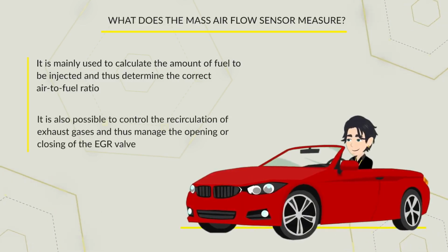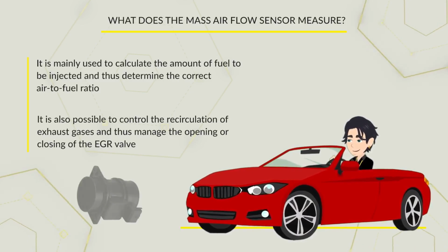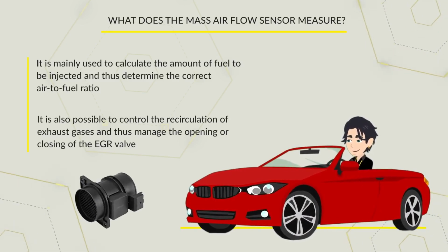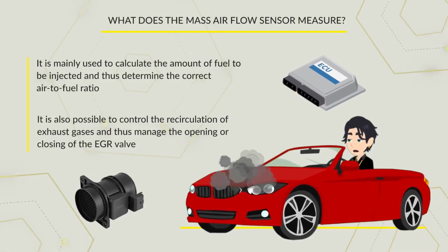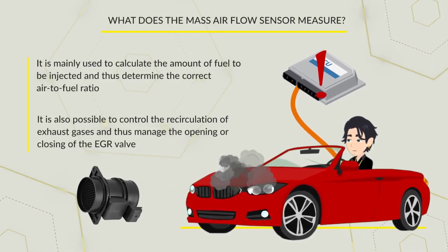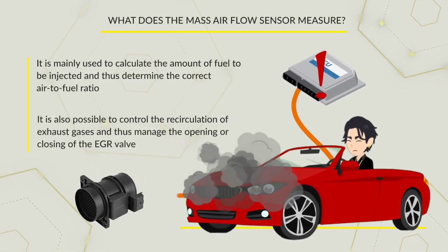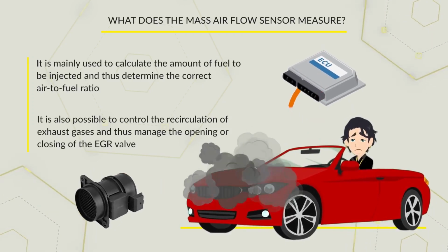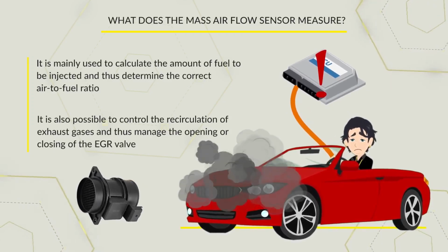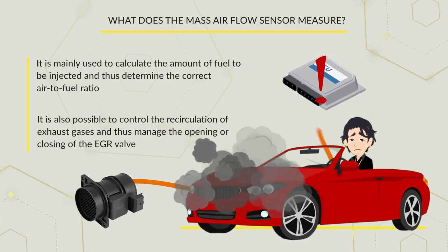Be very careful. A faulty or damaged air mass sensor can transmit incorrect input signals to the engine control unit, which consequently incorrectly drives other components. If the stress on the air mass sensor is high, it can cause irreparable damage shortly after purchasing a new vehicle, especially in turbo diesel engines.